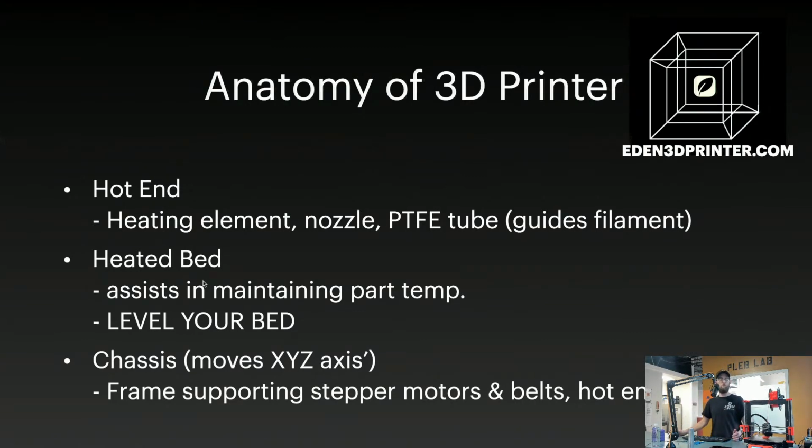The plastic is hot, the bed is hot, it wants to stick. You can see it's not moving. Let's cross our fingers and make sure that it continues to do so. I did wash it prior. Make sure you level your bed. The first layer is always the biggest issue. Level your bed, level your bed, level your bed. That's your foundation. If you don't have a solid first layer, the part will probably fail.